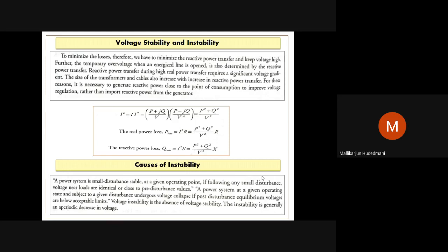When I take into account voltage, the system is not able to maintain its stability, is unstable, when it delivers its service to the loads, due to the demand for reactive power, voltage gets affected. Not maintaining its voltage within the specified range becomes a threat and challenge. So instability results. This is a very oscillating phenomenon, and it will protrude into the system and cause many of the components to start oscillating, fail and malfunction.